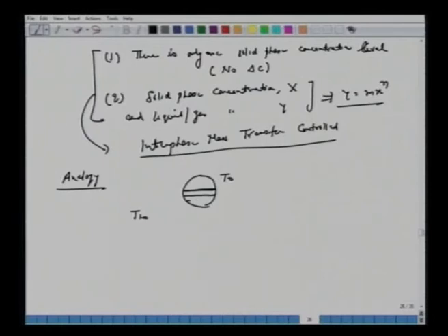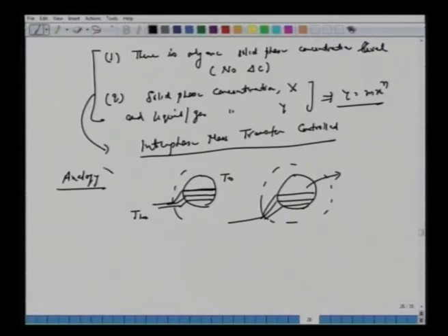The temperature will be uniform inside, and whatever drop occurs will occur across the film. If it's iron or copper, with very high thermal conductivity, there is one temperature, and all temperature gradients appear only in the film transfer in the liquid. This is the same analogy we are making for solid adsorption. So that's our physical understanding. Now we can set up some calculations.